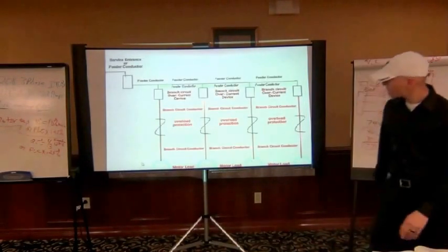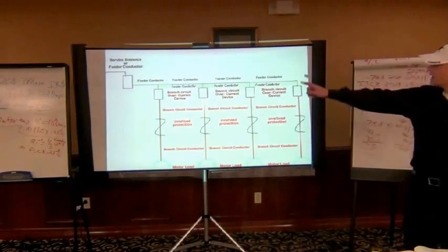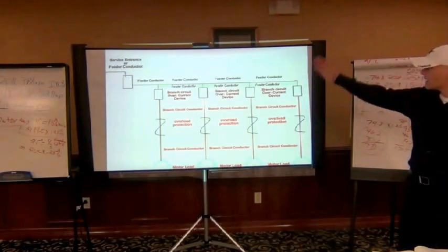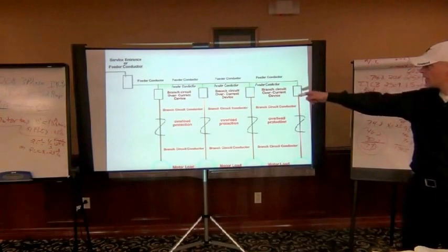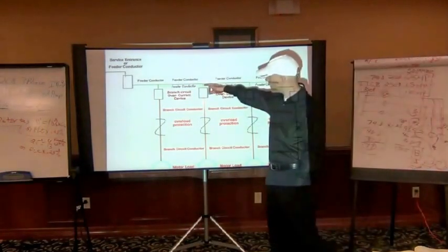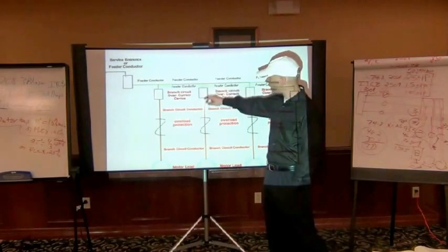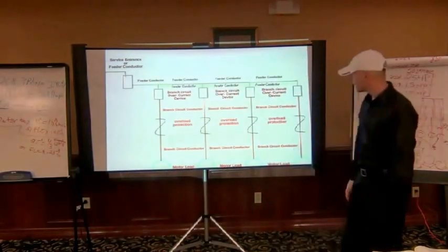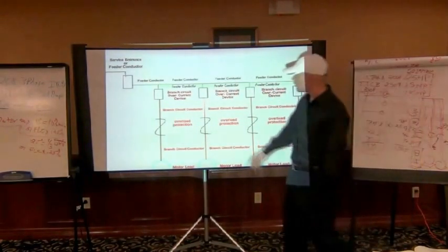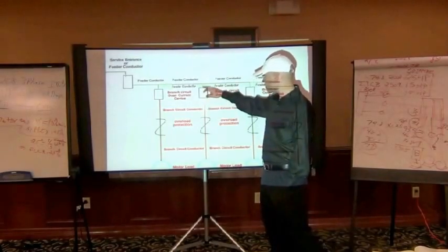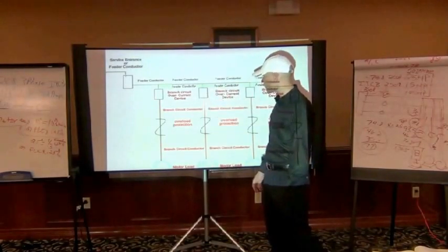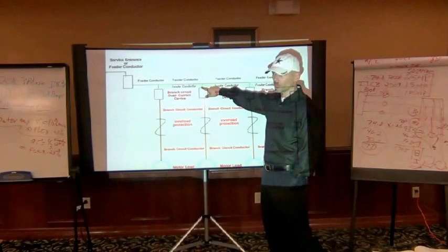Now, just a kind of a smaller picture of it. Again, breaker, feeders, individual branch overcurrent device there. This tap rule here and this tap rule here are going to be different. A feeder tap is right up here, and then these are branch circuit taps. This is usually where you have your 10% rule, because this is going to be a pretty short run most of the time.